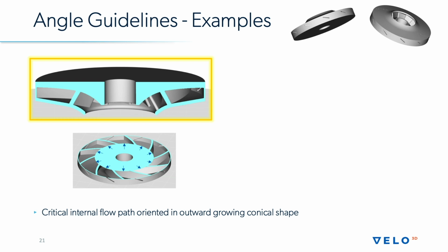And if you look at this down-facing surface, it propagates from about 30 degrees here in the beginning, and then, to give you some size, say this is about 10 millimeters in Z height span, it goes down to about 10 degrees at the end. And so what you've got is this dynamically changing, outward conical growing shape, or this convex shape. You have the dynamics of some real parts where you can look at the constraints that the veins pose, and you can also start to infer some things about the planar geometries.